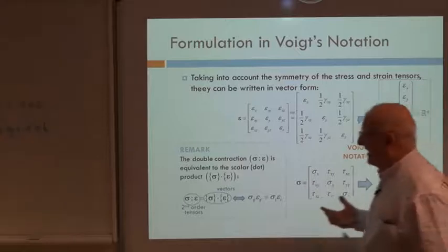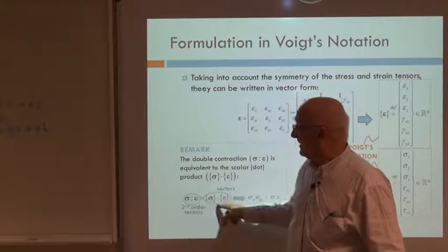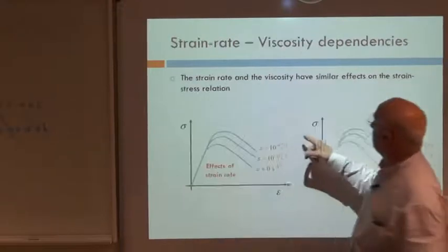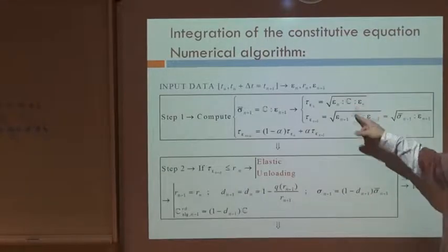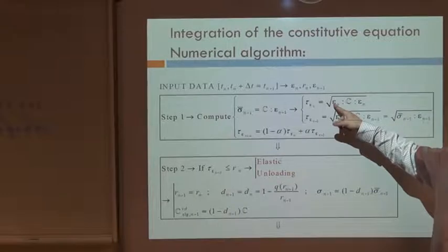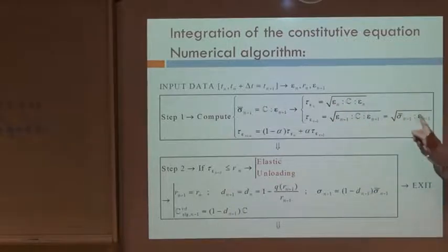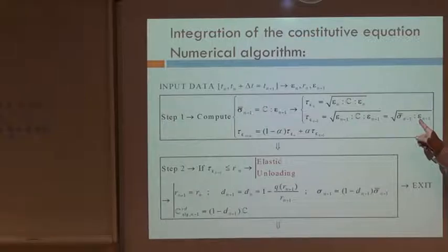So what does it mean? That, in fact, the only complex operations I have to do would be multiply double dot products that appear in several places. Here, no? You see, for instance, where? Here, these operations, and the operation can be replaced. Instead, every time that it appears epsilon times a vector here, I can replace them by the vector of effective stresses, 6 components, times single dot product, the vector of strains. Okay? So it's much simpler to code, much more effective. There is no repetition of computations and so on.